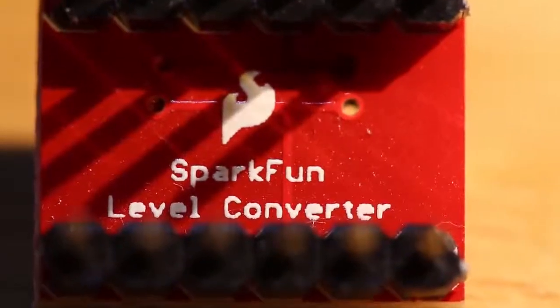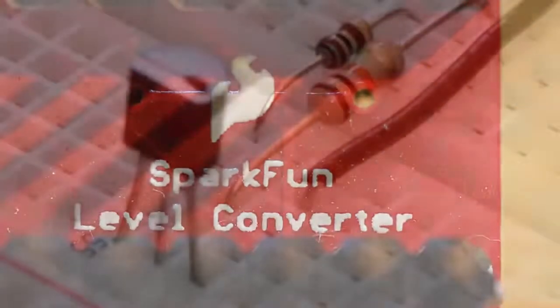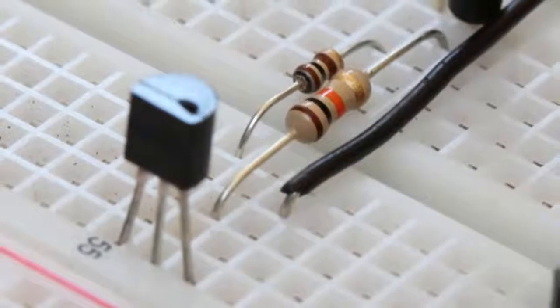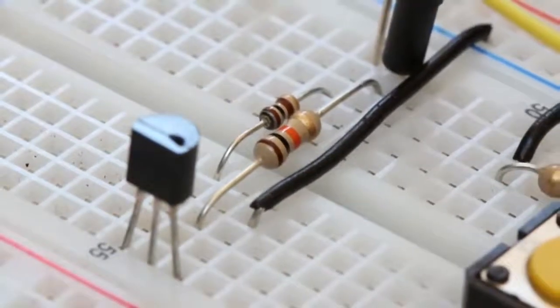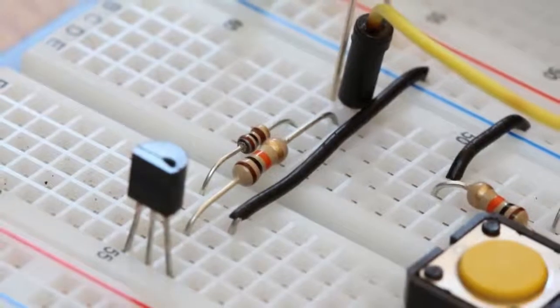There's a great little board available for this task from SparkFun, but just be careful with voltage and current levels. For example, in my example that I'm going to show here, I will use a transistor to protect the GPIO in switching on and off an LED, which typically has forward currents of about 20 to 30 milliamps. All of the GPIOs can be configured as inputs or outputs, which I will also do in this video.